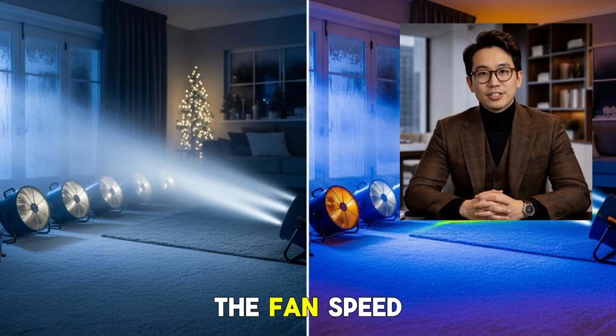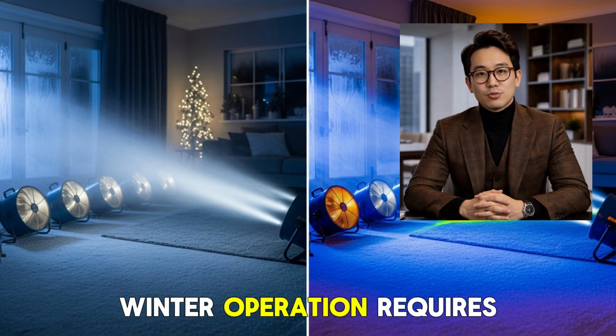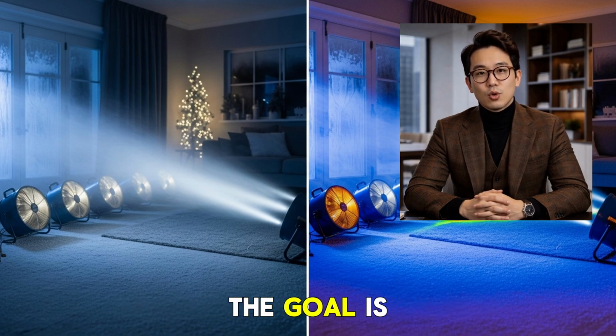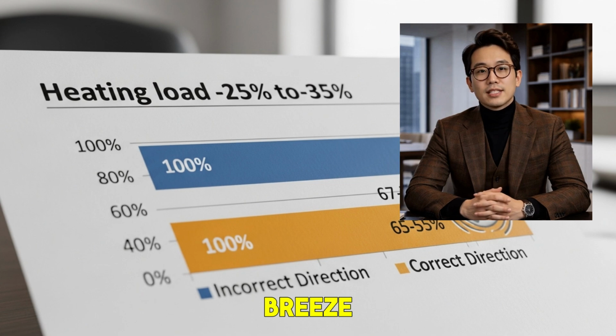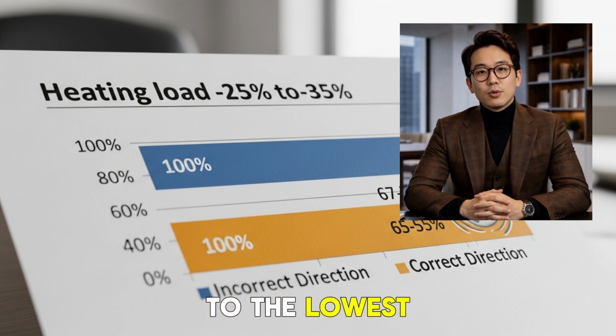This happens when the fan speed is too high. Winter operation requires low speed only. The goal is gentle circulation that redistributes air without creating perceptible breeze at occupant level. Set your fan to the lowest speed setting.